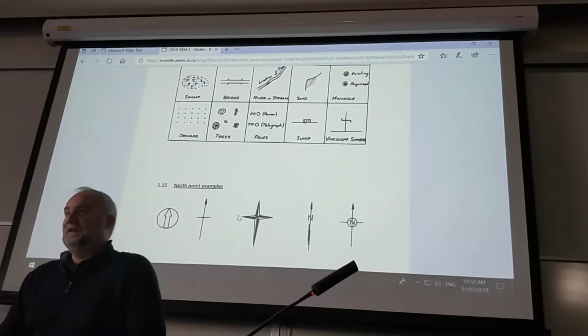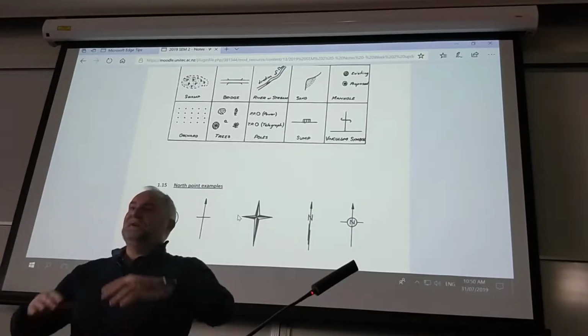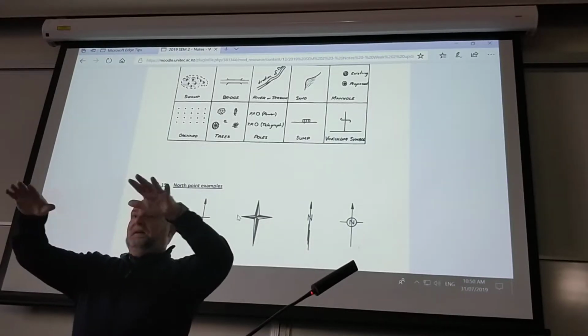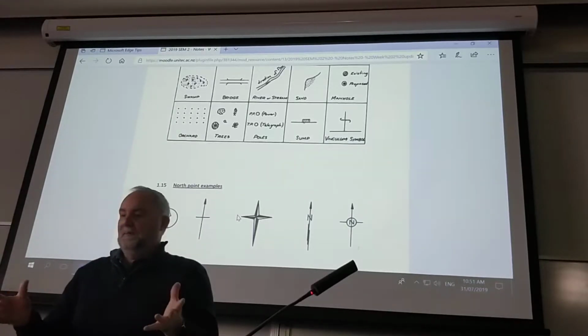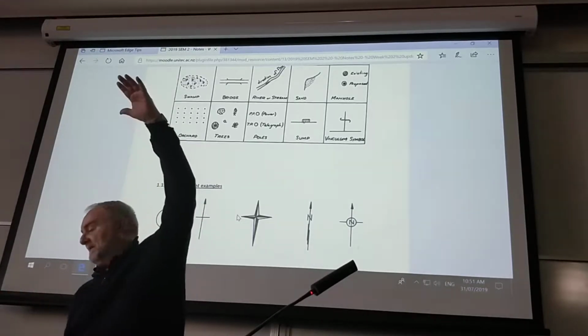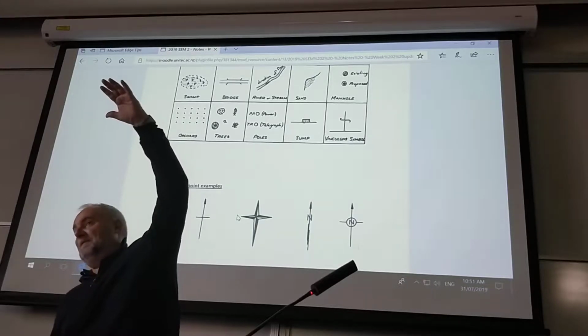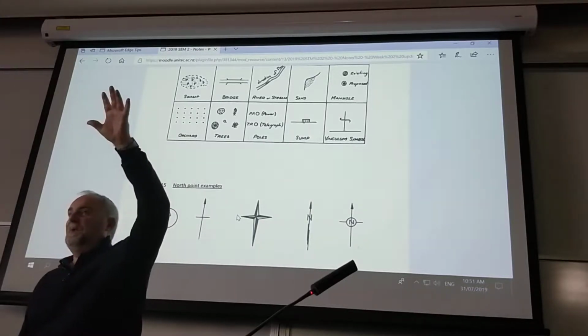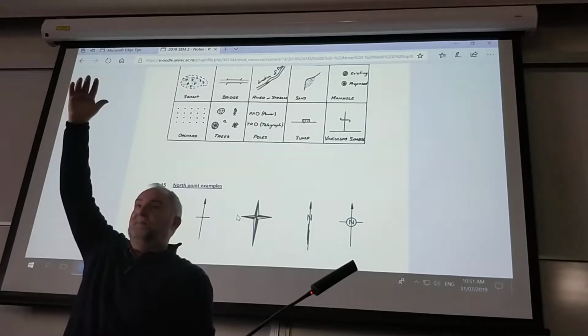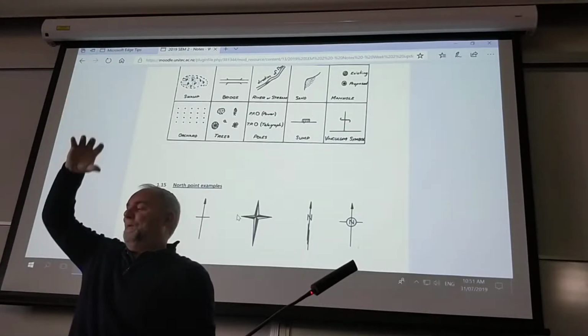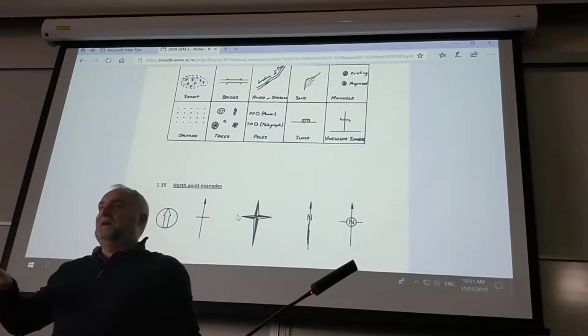There are 3D trees. You insert a 3D tree, and you think looking down on it, the tree is right beside everything else, but in the view, in reality, the tree might be inserted at 0 ground level, and the rest might be at 50 metres, or the other way around, the trees come in at 100 metres high. So just be careful. You're creating issues that you don't need to create in AutoCAD.